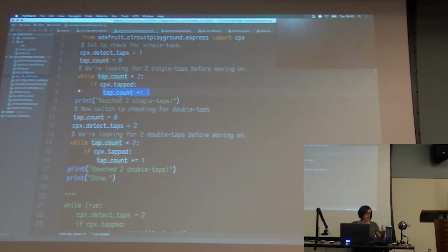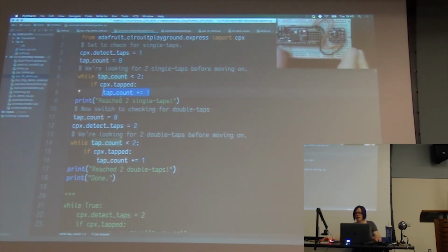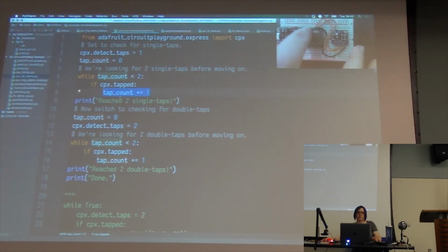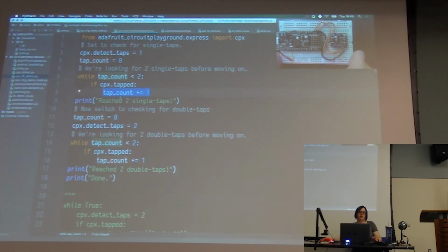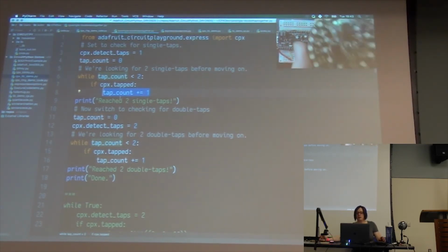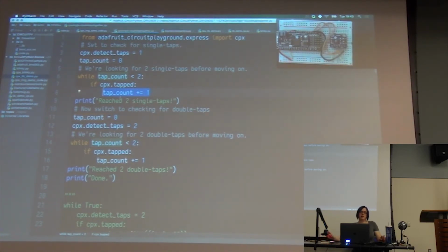There are different sensors. In fact, this is a gesture sensor. It has an interrupt pin, and you can set it to work off of a digital output. It doesn't necessarily use it like you're thinking. That's what we tried to get the accelerometer to do for the tap detection on the Circuit Playground Express. That was five days of fighting to find out that the chip is designed weirdly and doesn't really support what we were trying to do.